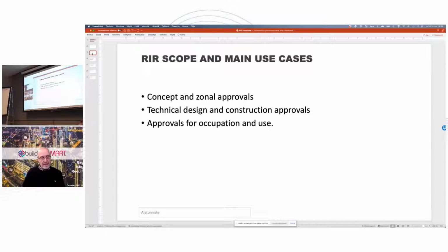And the third part is additional documentation. Maybe it's an operational manual that needs to be attached to the information exchange. So these three parts together form the exchange requirements. So geometrical, alphanumerical, and documentation. So that's how we specify the use case. And it is a big job.